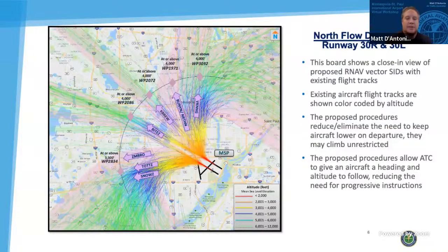Thanks, Brian. Yes, as the plane is departing Minneapolis, most planes climb to 7,000 feet, and our arrivals are descending to 8,000 feet. So it is up to us to get those departures on course as soon as we can and at a safe altitude to transfer to the Minneapolis Center, who then climbs their planes to the flight levels as cruise flight exists. And then as we get to the center environment, that's where Sean will take over and explain some of the center.